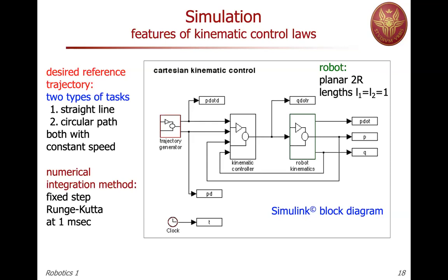We will integrate the closed loop system. So we have the robot kinematics, and we are assuming no dynamics here. We're assuming an ideal model for the dynamics, that the low-level control loop works perfectly. So in the simulation that you will see, I don't exploit the fact that we may run into the limited bandwidth of our low-level control loop. So we consider ideality. Then the kinematic controller could be a joint space or a Cartesian kinematic controller.